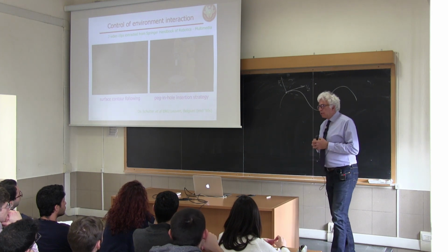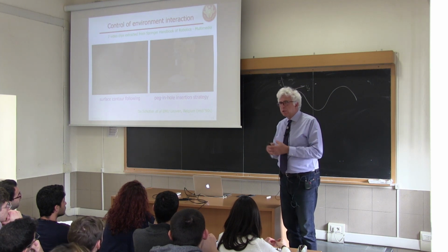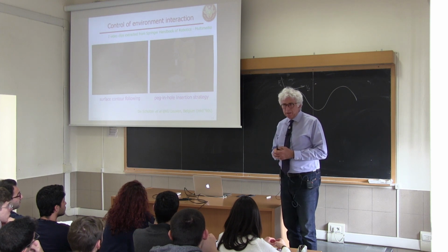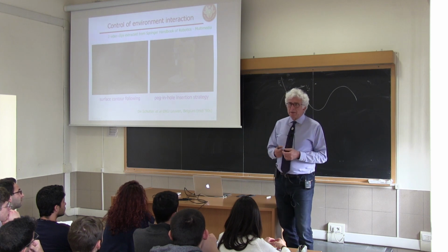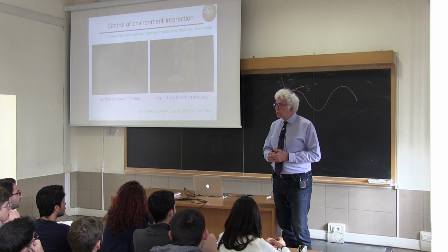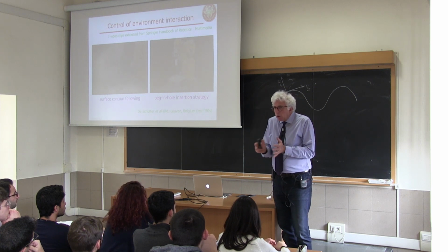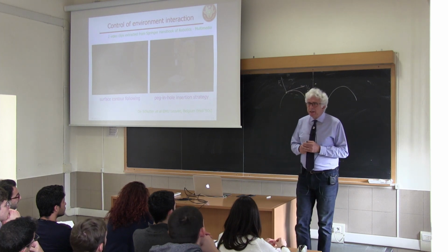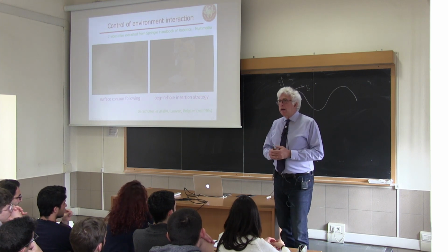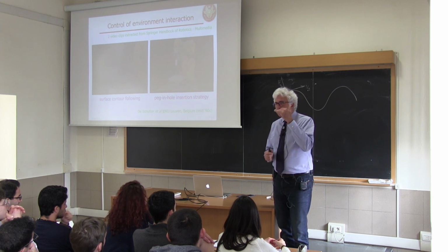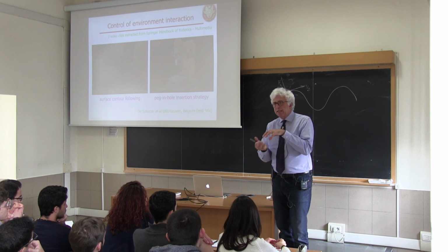Well, if you remember, when dealing with components of robots, we mentioned the existence of a device which is similar to a force torque sensor mounted on the end effector, which is called the remote center of compliance. It is mounted as an end effector of the robot and can accommodate in a passive way forces arising from the contact with the environment, so that the robot does not know anything about contact or not. It's programmed to move in a certain way, and the small errors that you may get, for instance, in the insertion of a peg in a hole, are compensated passively by this device, which consists of a number of springs that will move the bottom plate of the RCC device with respect to the top plate, which is bolted on the end effector of the robot. So the robot does the programmed motion without caring, and the passive device does the job.